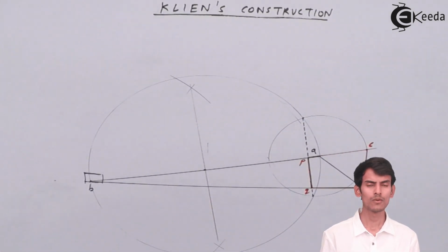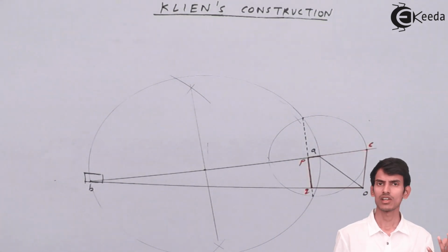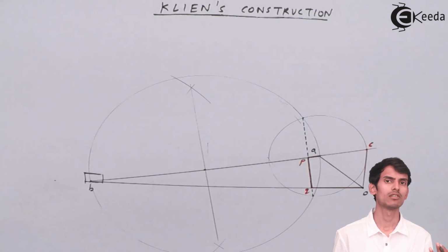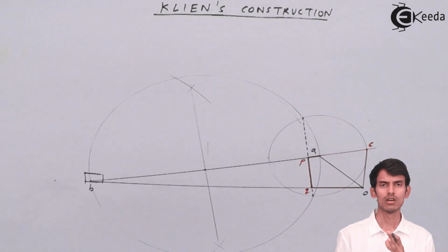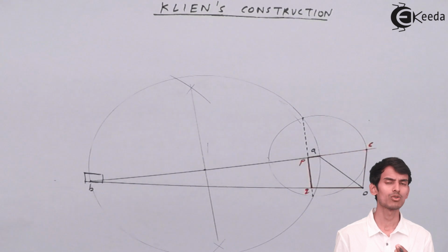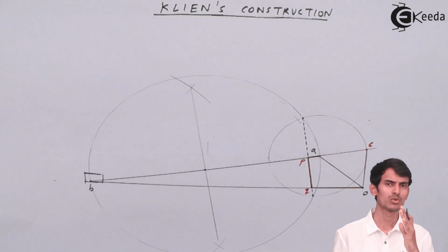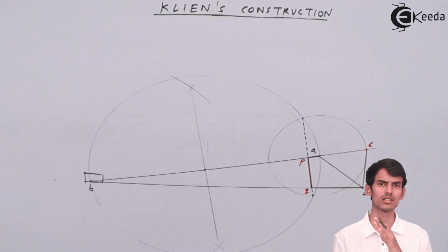Last is OQ. Since it is horizontal, and the slider has a linear, horizontal motion, it represents the acceleration of the slider. The slider will have acceleration because it has to go to and fro, and a to and fro motion cannot be a constant velocity motion. Once it goes towards one end, it has to stop and return to the same position.